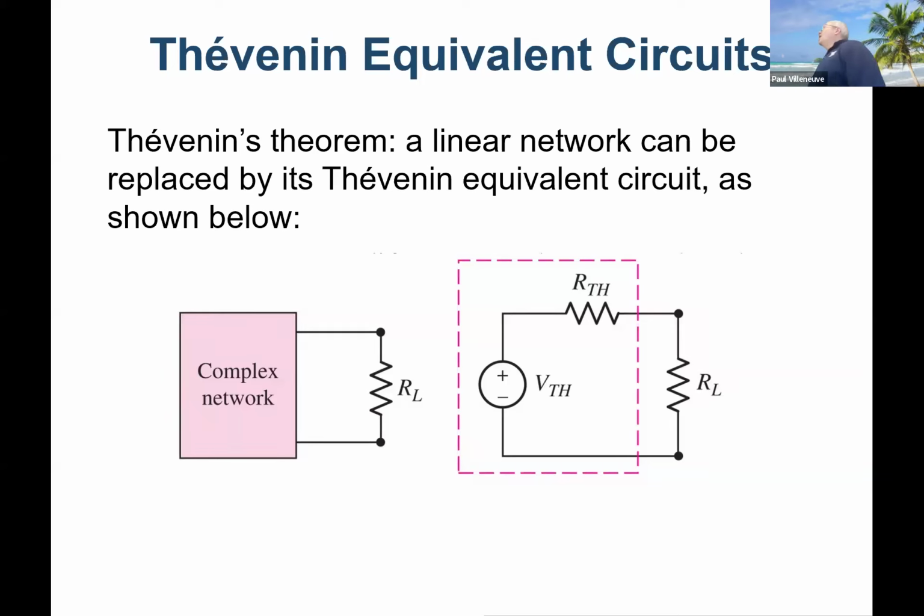And again, the whole concept of Thevenin and Norton, and you all know about Thevenin and Norton, is really just to simplify a lot of future circuit analysis, right? If we can find Thevenin and Norton equivalents, which basically tell us I can have this incredibly complicated circuit with millions of different components, and as long as I replace that with the proper either Thevenin or Norton equivalent, it doesn't matter if I have 10 million elements or those two elements, the circuit's going to respond the same to the external circuit that you apply to it.